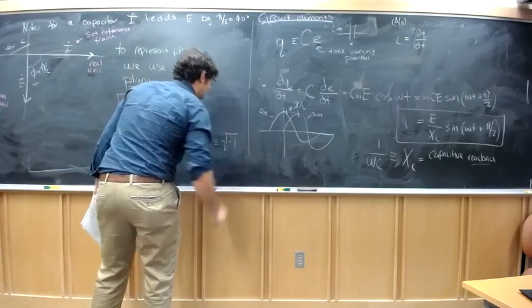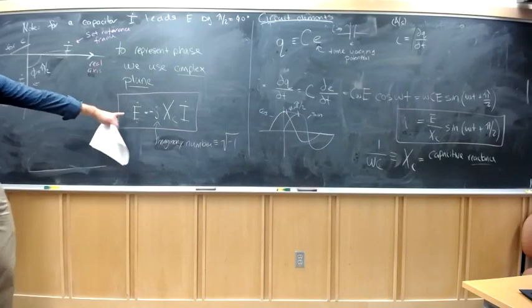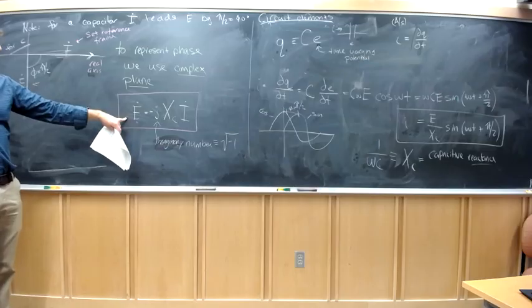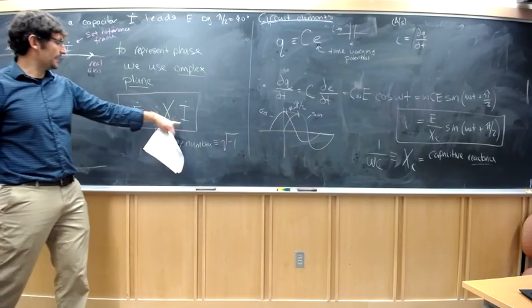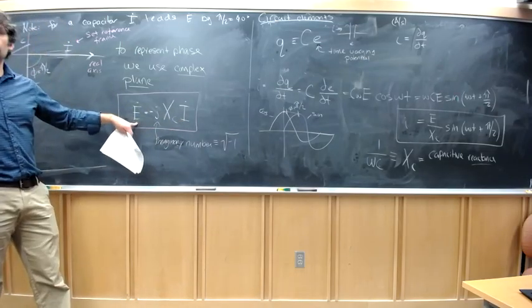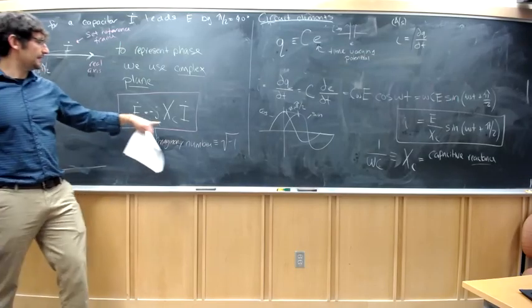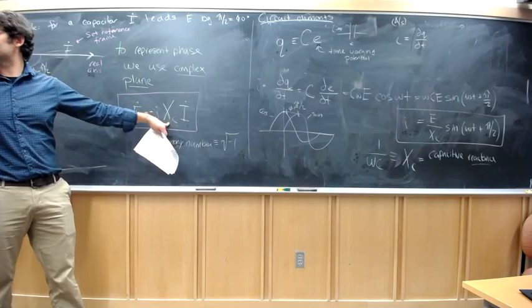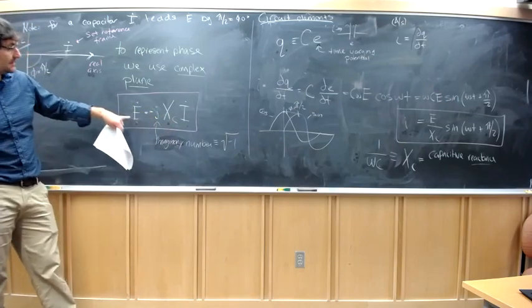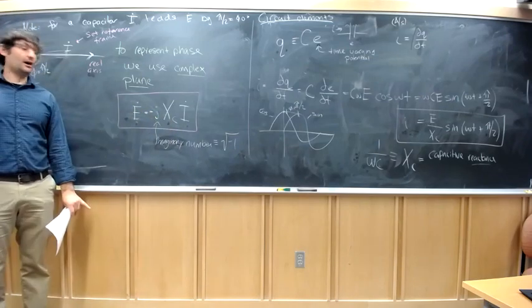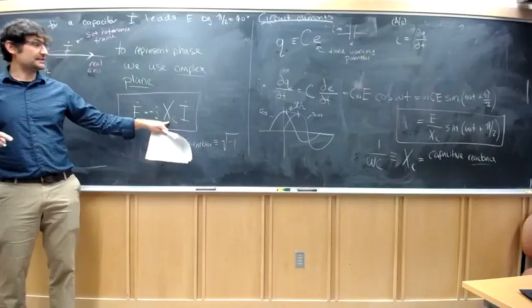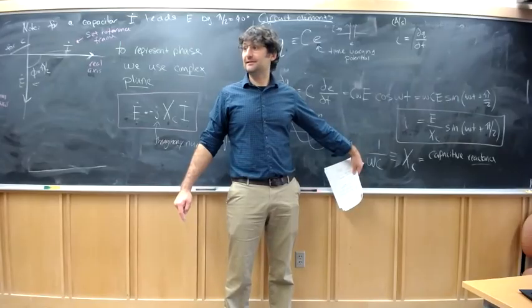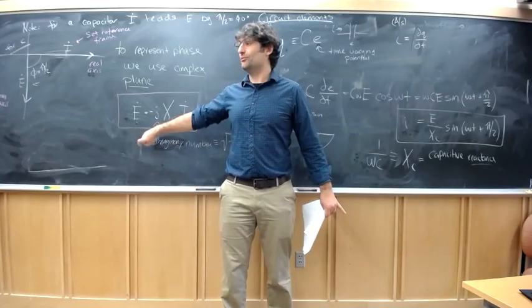Square root of -1. But this is nice, right? It's a very compact way of writing the relationship between the voltage perturbation and the current response in terms of something that looks kind of like a resistance. So not only is it a capacitive response, you have to make your resistance essentially frequency dependent, right? That's what it's saying. So this is like Ohm's law.